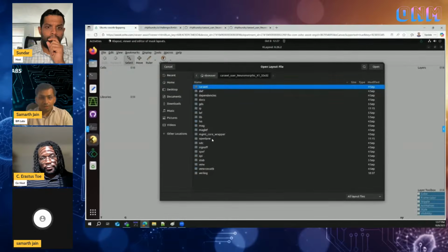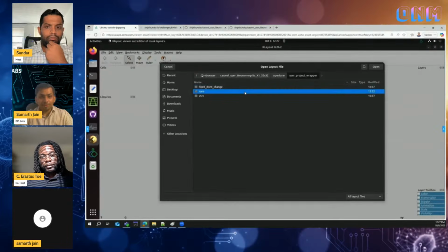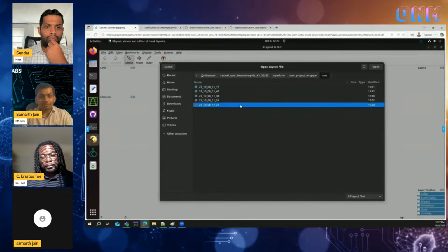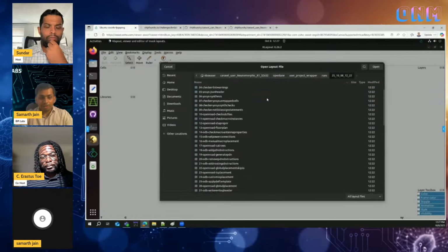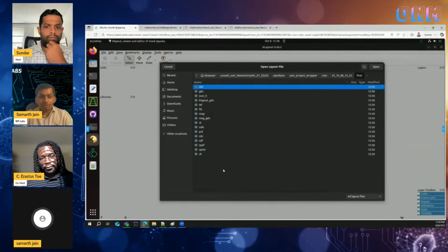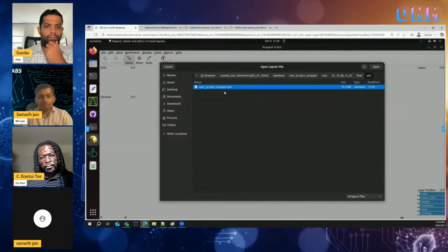So it should be under the OpenLane folder. Runs. Yeah, you can go under runs. You can check the latest run. Yeah, so I mentioned it will generate a report for every step. Because our design, the sample design which we have on the Git, passes all the tests, we can just see the final reports. It generates all sorts of files. GDS is the one which we require. So we can just import this file and view our design of the IP.